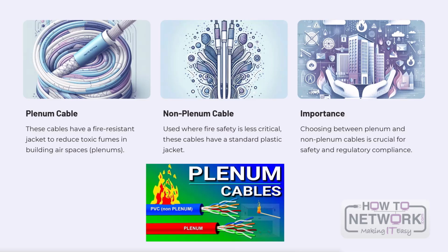Let's talk about plenum cable. Plenum cables feature a fire-resistant jacket designed to minimize toxic fume generation in air spaces. Within buildings, these spaces often house critical infrastructure like wiring and ventilation systems. This special jacket helps limit the spread of fire and harmful smoke, enhancing safety during emergencies. This one is the plenum cable.